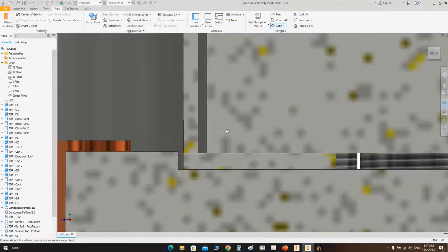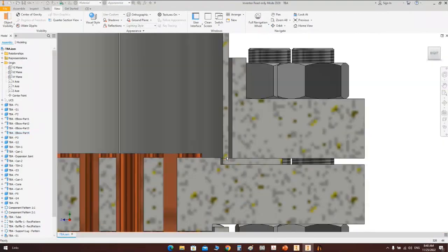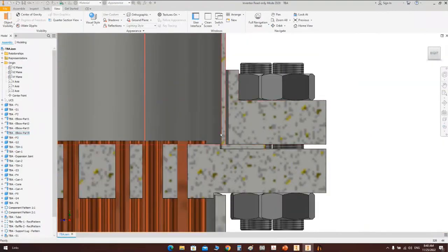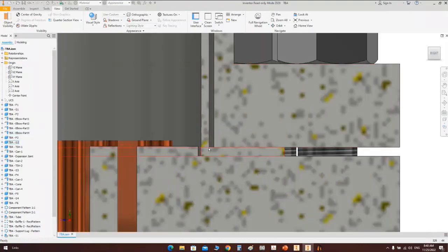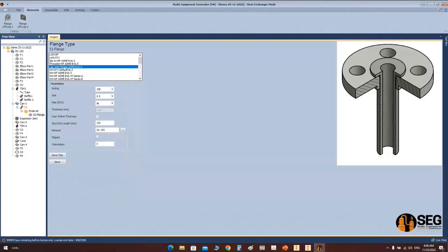As we did here, we use this feature, which is linear flange, as a metal gasket here, and it will be welded with the shell element or the plate element like that. So you can use this type if you would like to make something looks like the lap joint. But for nozzles, you can use this type, which is lap joint flange with that configuration.